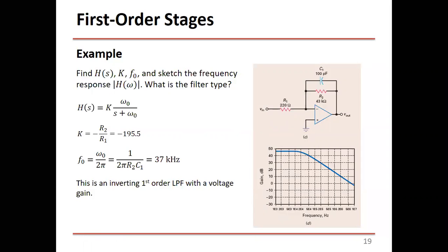In this example, you have a capacitor. You don't do anything with it. At low frequency, this capacitor is open circuit, right? In this range of frequencies, where you have a flat top pass band, the capacitor is infinity, it's open circuit.